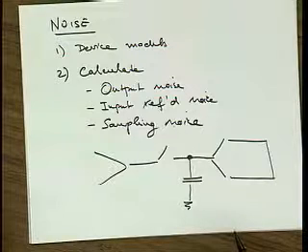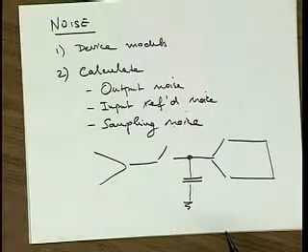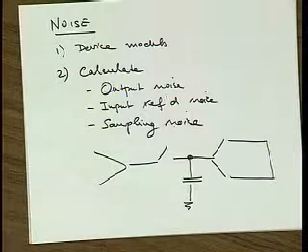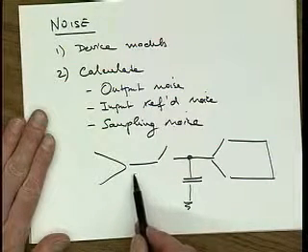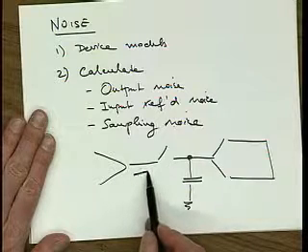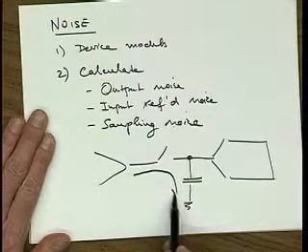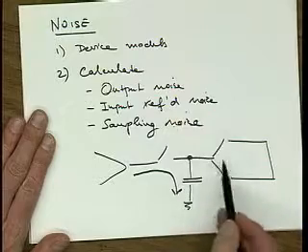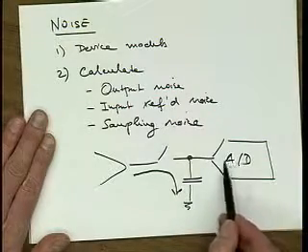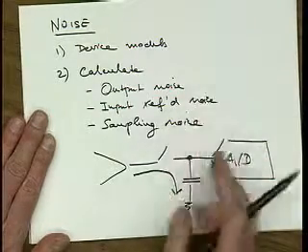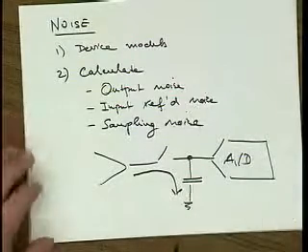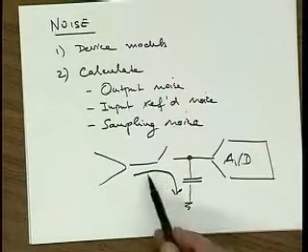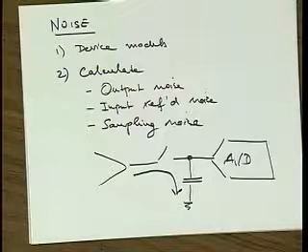It may sample at 100 megahertz, but that still means that once every 10 nanoseconds it's actually going to look at the signal and convert it, and for the rest of the time, it doesn't even look at the signal. So now what's going to happen is that the signal and also the noise are going to travel through this path, and let's assume that the A to D converter actually has a very high input impedance, so it really doesn't do anything. We just model the entire A to D with this capacitor. Right? But then the signal and the noise are both going to end up on this capacitor.